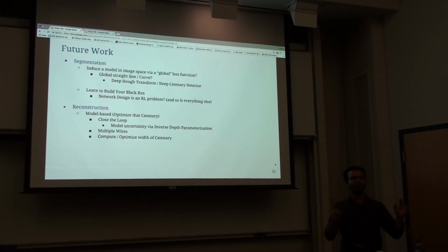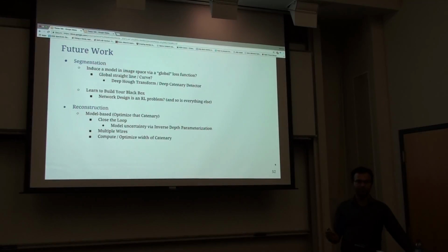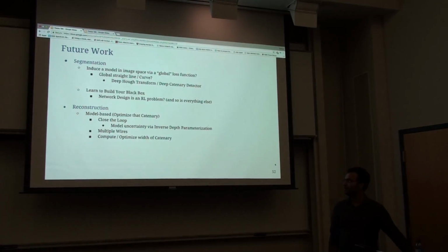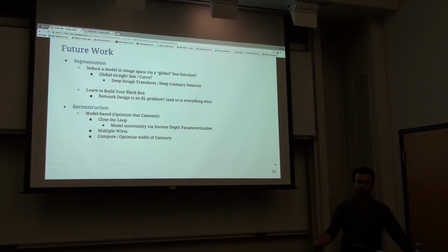And if you remember that false positive in which we converge to the wrong yaw value, either we can compute the width of the catenary just because we know the camera calibration matrices and we know where the extent of the intersecting regions is from our odometry. Either we can just come up with a maximum fixed width and that would work, or else we can put that as part of our optimization problem in terms of parameters or just changing our objective function.